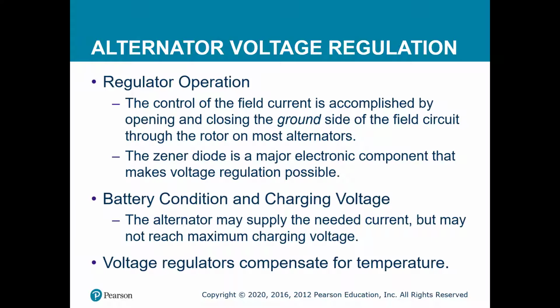One of the things that you may come across, and we discussed this in the battery section, was battery registration. Based on how long the battery's been in the vehicle or when it was last installed, you may have to perform a reset procedure to let the charging system know just how old the battery is. Voltage regulators can compensate for temperature as well.